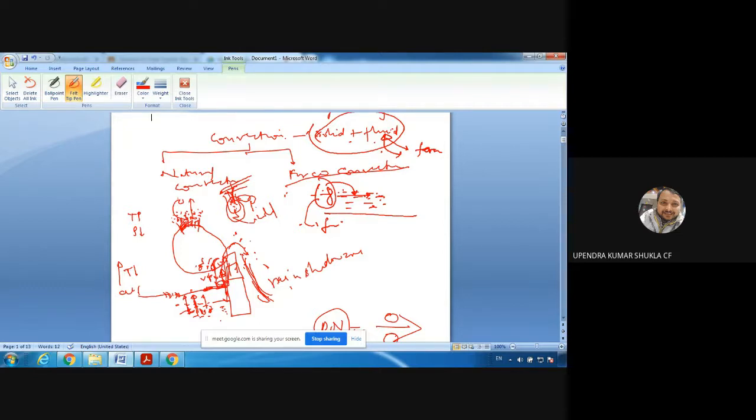Here, due to density difference, a buoyancy force is created. So the motion is generated due to the buoyancy force, and hence the temperature distribution plays an important role in determining the motion in the case of natural convection. But we know the motion determines the temperature profile. So the equation of motion and energy balance must be coupled. In a way, we can't neglect any one. So we have to solve the equation of motion as well as the energy balance simultaneously.